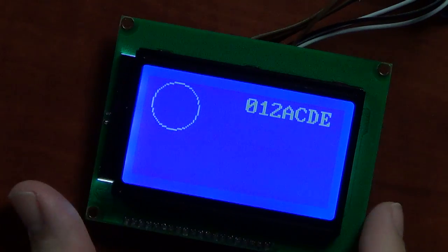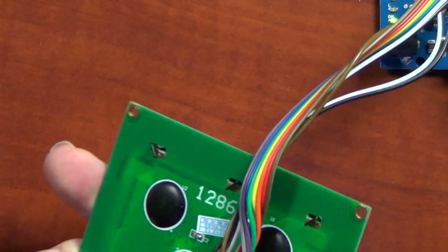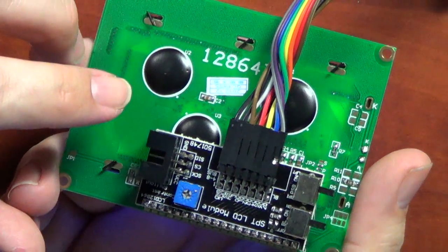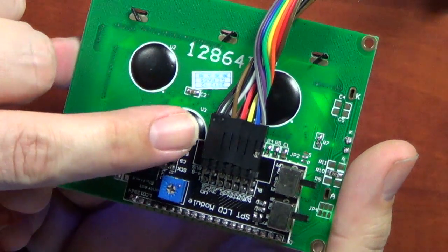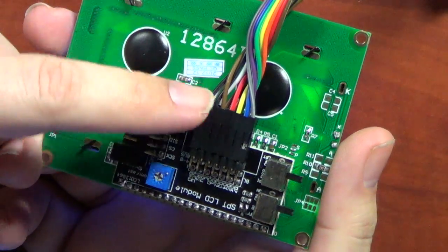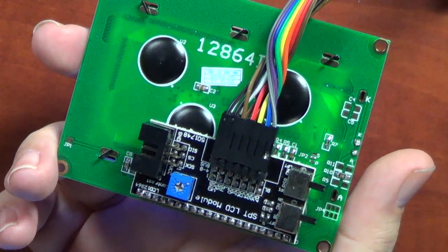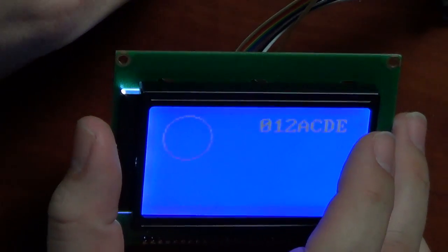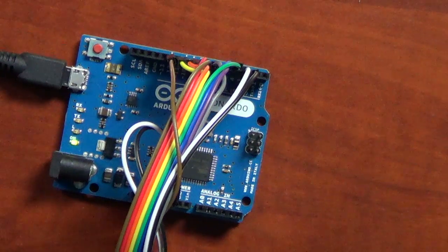This is the graphical display. Now this is still a parallel interface. In fact, if you look at the back of this, you're going to see I have a lot of wires going in here because this actually requires an 8-bit interface. I can explain that in a little bit. But we still have power, ground, your 8 different data channels, and you have RW, the same pins you had before, your E, RW, all that's in there too. And it's going to a different Arduino, which I have right here, just an Arduino Uno like I used last week in the demonstration. So you see I have all the pins wired up to it.